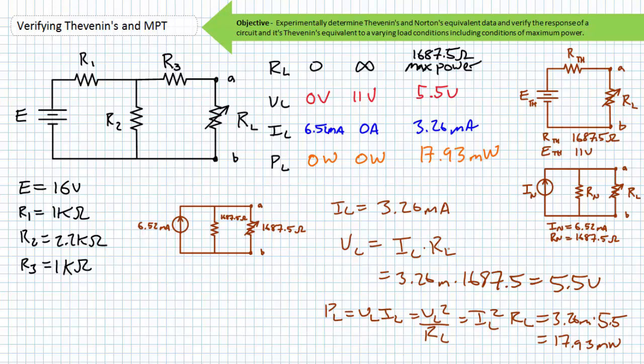If this has not convinced you of the utility and ease of Thevenin's theorem and Norton's theorem, I don't know what can. Every time the load resistor changes states, it necessitates another tedious series parallel circuit analysis if you use the original series parallel circuit. If, however, you utilize the Thevenin's or Norton's equivalent circuit, it is a simple pure series or pure parallel circuit that quickly and directly yields the desired values using the most basic of techniques.